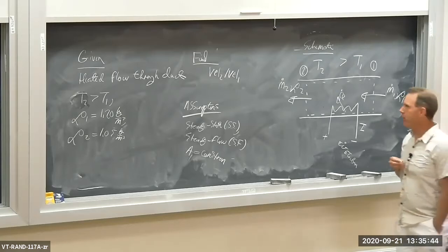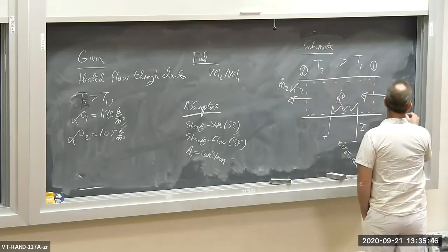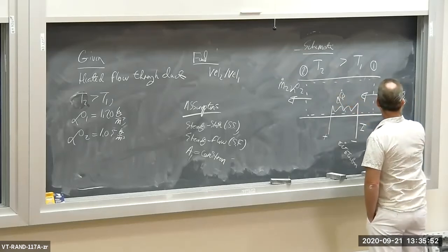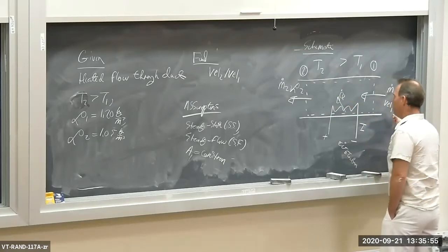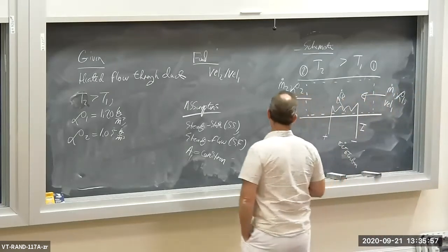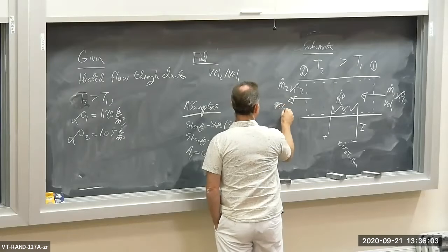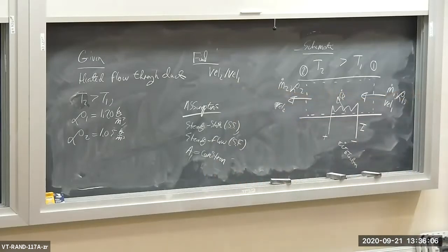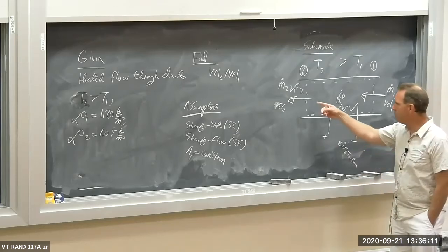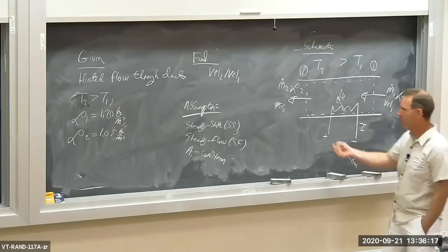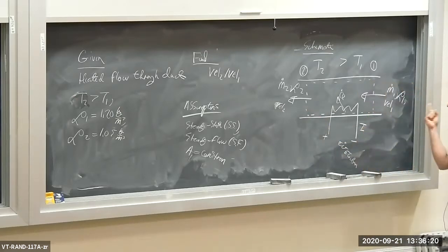Now, what are we supposed to find here? The air flows in at a certain velocity. So we have an area for the duct. The velocity on the right is VEL1, and the velocity on the left is VEL2. So I want to know what the ratio is of the outlet to the inlet velocity. As the air heats up, becomes less dense, presumably the volume flow rate goes up and the velocity goes up. Hopefully the air is coming out at a higher velocity than at the inlet because density is going down. And you'll see this in just a minute.